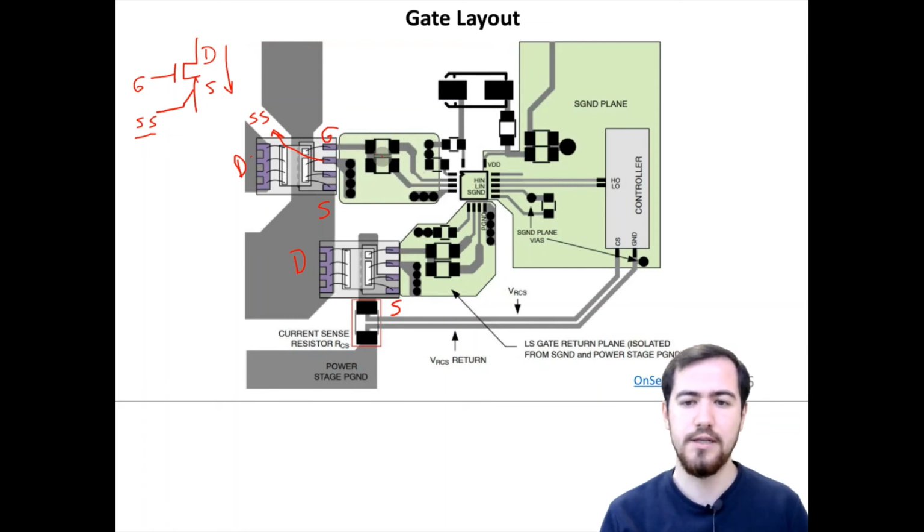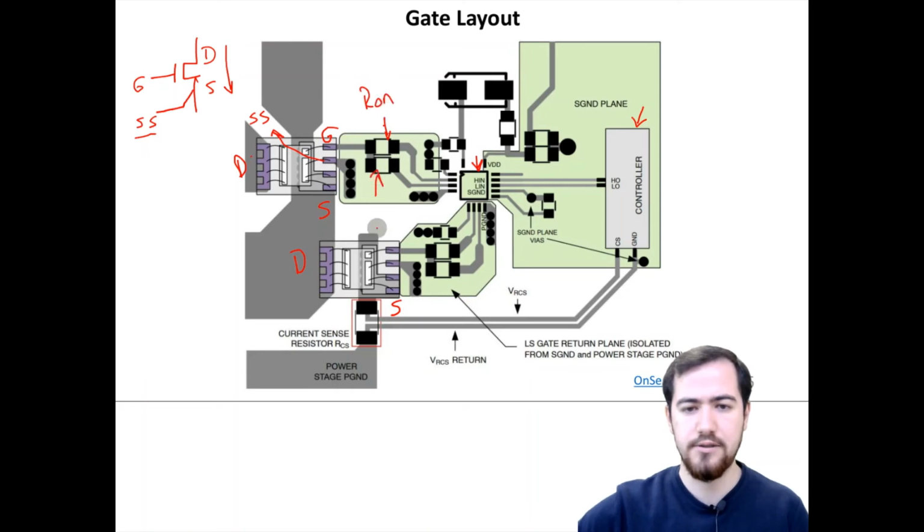So let's figure out how the current is supplied, but first let me define the circuit components in a better way. This is our microcontroller, and this is our gate driver IC connected to high side and low side switches. This is our turn on resistance. Let me write it, turn on, and this is our turn off resistance. So let's clear this screen and define where the current flows for a turn on instant.